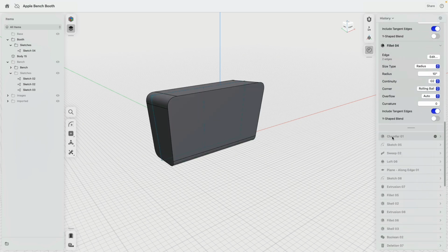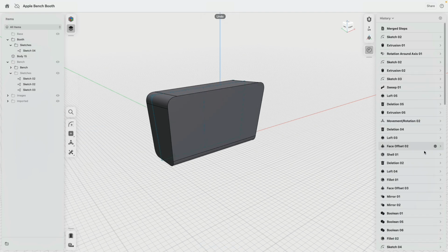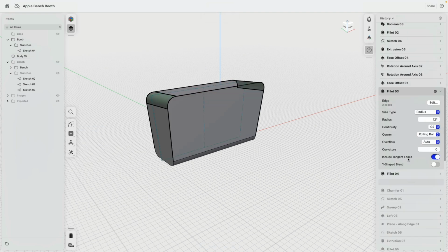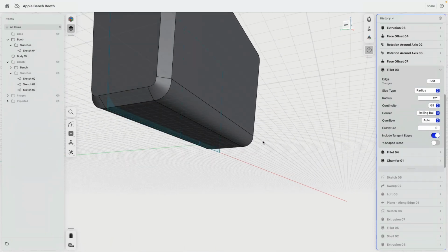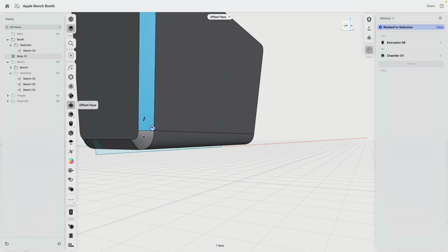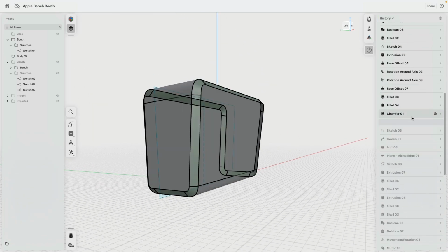I want to run actually a profile across this line, but that's a line, and with a roller coaster, you have left and right track, and the track surface bends. Okay, I don't have a track surface. What's the easiest way? Well, we use the chamfer command. So I then actually added a chamfer command. So I flattened that edge. Now I have actually a surface along which the sweep command can run, which is pretty cool.